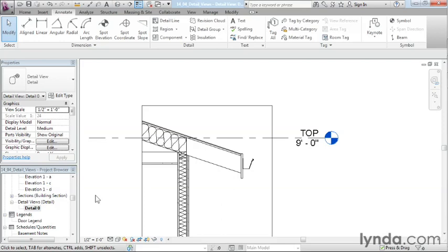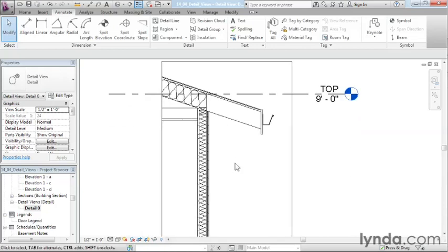But to make a long story short on the detail work that's going on in here, you just draft on the inside of this already existing three-dimensional object in order to put in the final details. There's no reason to have all this information modeled in Revit when you can just use a few lines and keep your Revit model moving quickly. The more information you put three-dimensionally in Revit, the slower the Revit model moves.